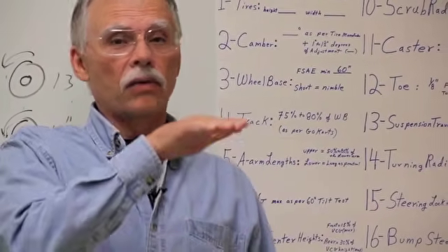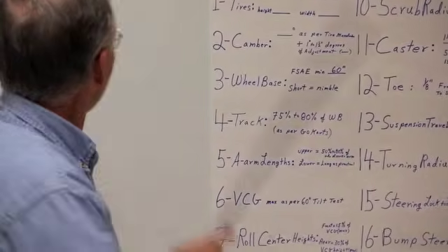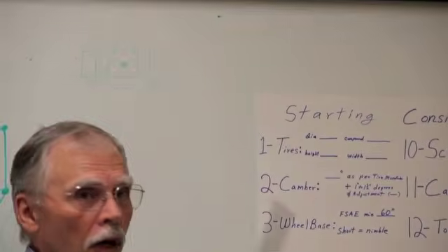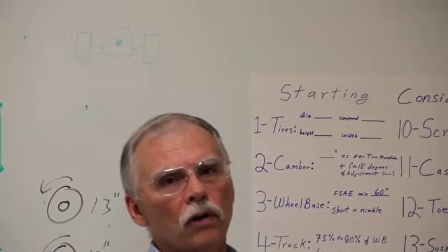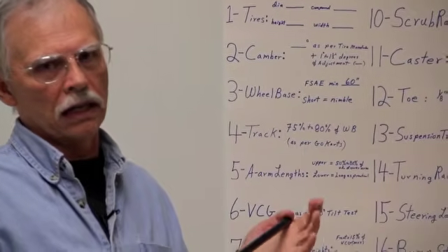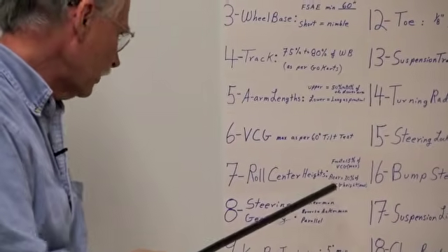Because as the car rises, the center of gravity rises, and then things tend to go downhill, and the center of gravity could go up and get outside the accepted envelope and could get up on two wheels or even roll over on its side if you had enough jacking effect. So jacking effect should be minimized. All right, just that simple.